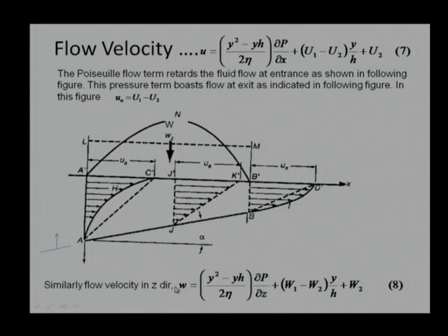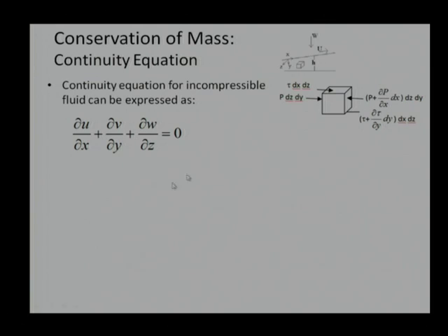To do that, we require an additional equation, what we call the conservation of mass, or many times we use the word continuity equation. So, that comes out here, this conservation of mass. We are making one assumption that density is not changing, that it is an incompressible liquid. So, density will not depend on the x direction, z direction or y direction.